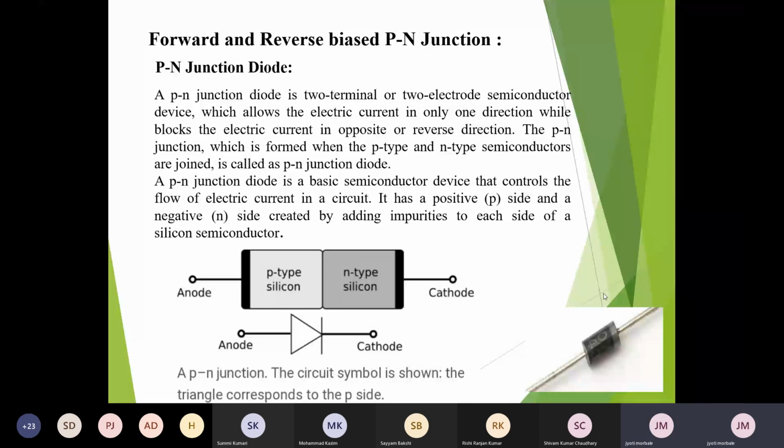When PN junction is formed, the depletion region is created, as you know, and the movement of electron and hole stops. So current flow through unbiased PN junction is zero because of the depletion region. Now to make the current flow through the PN junction, we need to bias the PN junction. As here we are having two electrodes, biasing can be done in two types.